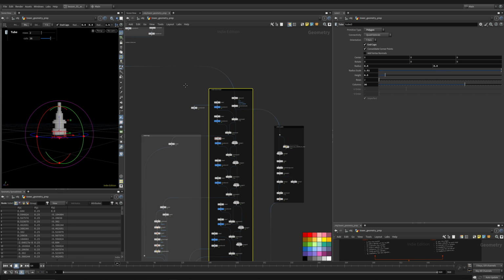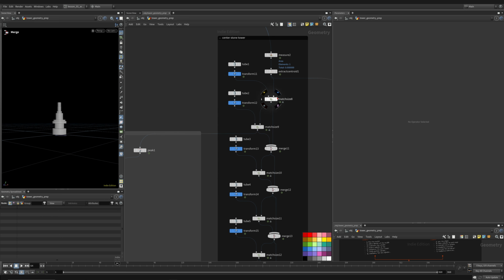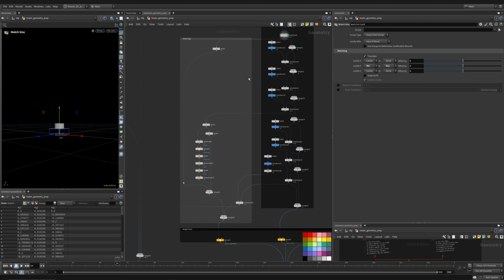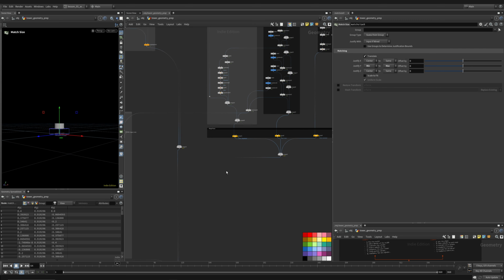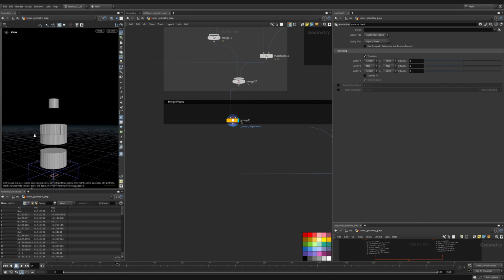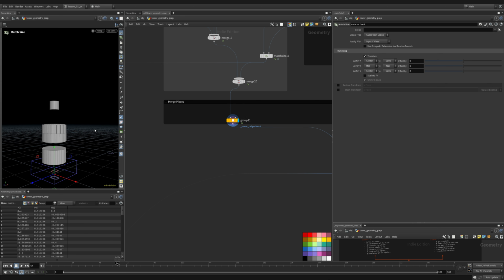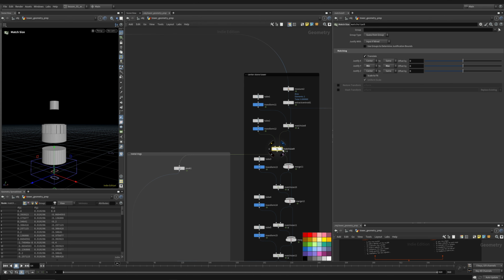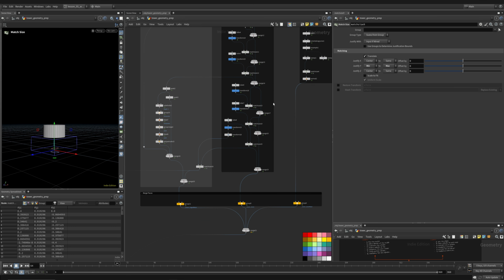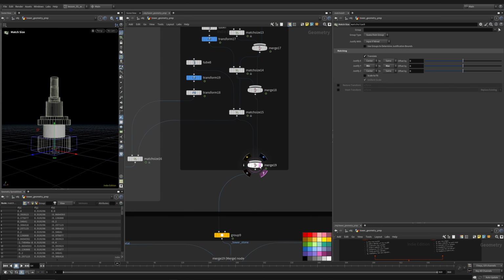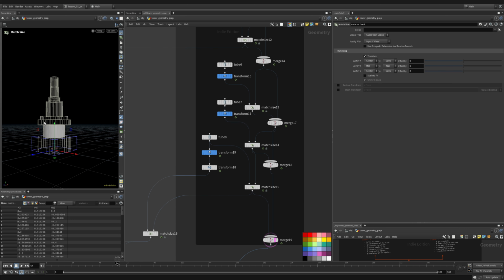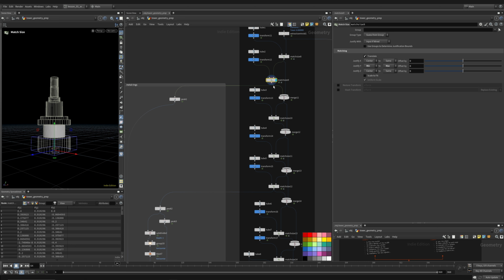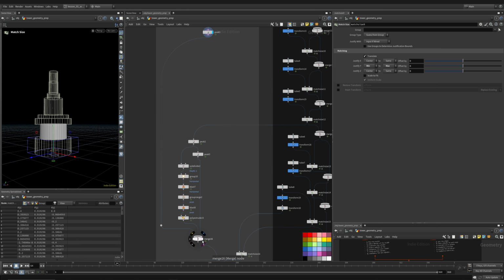And then for this other side, what I do use is I do break out a few of these because I want to create these rings that go around the center, and I want to randomize these and I want to make them metal. So instead of the concrete, I want these to actually be a different material. So what I did was I picked a few of these tubes where I liked the placement. So I'm going to ghost this one with this template flag. So I was like, all right, I kind of like this idea, this cylinder here. So let me save that out, make it a little bit bigger so it won't intersect our concrete.